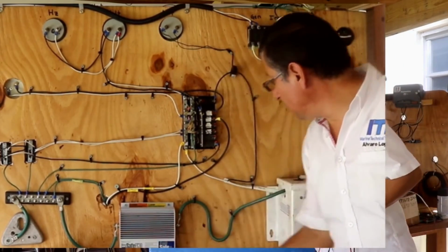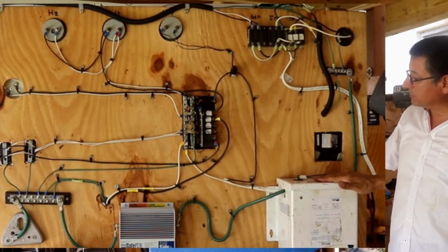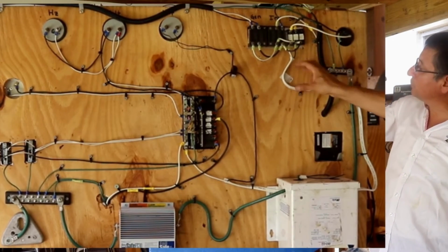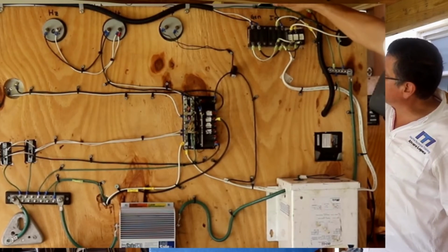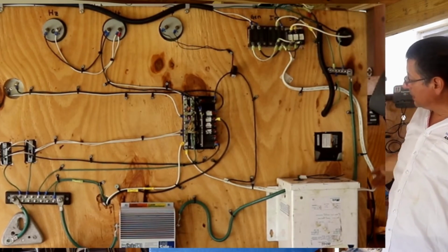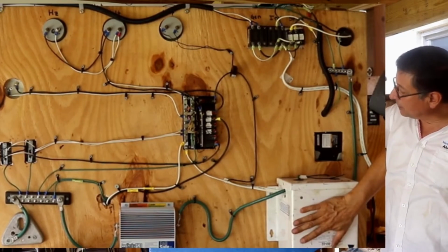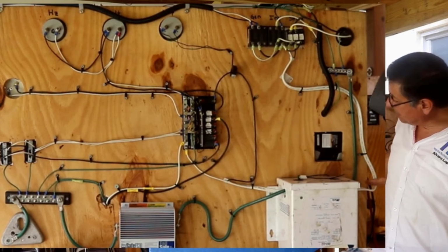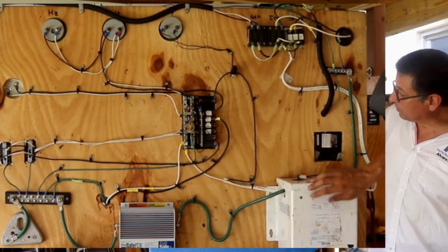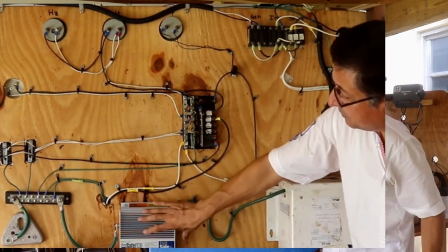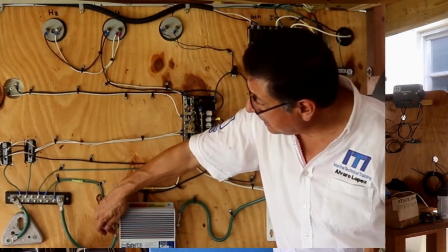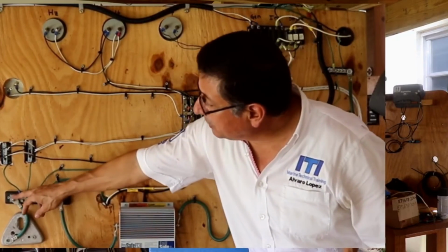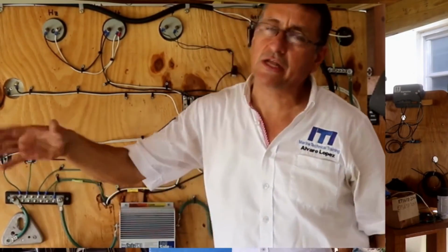Once again, the connection of the isolator transformer. The isolator transformer is connected in series with the main power coming out from the breakers or the switch selector. This is the switch selector and those are the individual breakers. The power enters the isolator transformer, and then continues into the main breaker. The ground goes directly, separated, passes through the case of the transformer, continues, is interrupted to introduce the galvanic isolator, and the ground continues into the bonding system. From the bonding system you have the sink, and the sink is connected with the water.